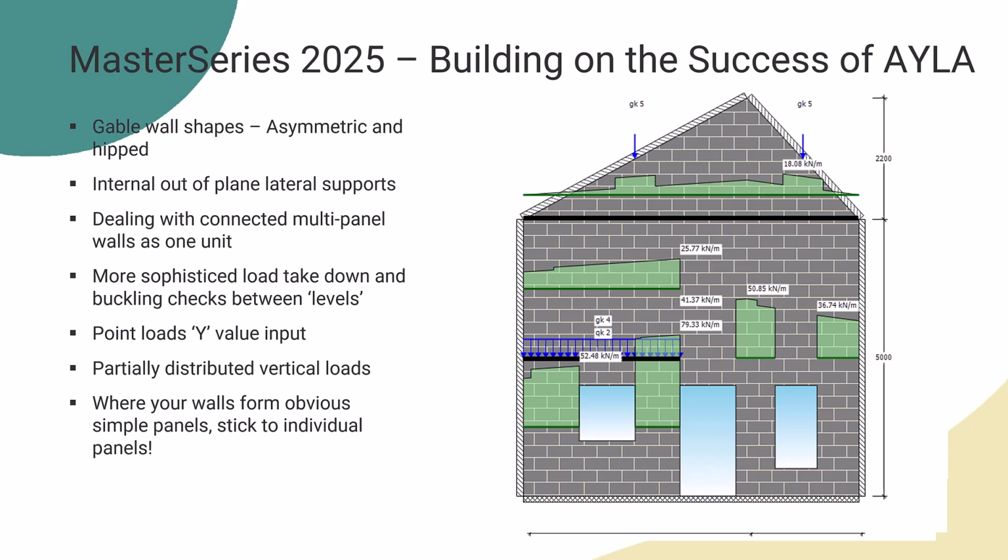So we'll be doing buckling checks on this strip, this portion of masonry, this portion of masonry, this portion of masonry. And then when we come across here, we've got a 5 meter height situation, and we've got the two strips here that load is being transferred onto, and we'll be doing buckling checks on those as well.